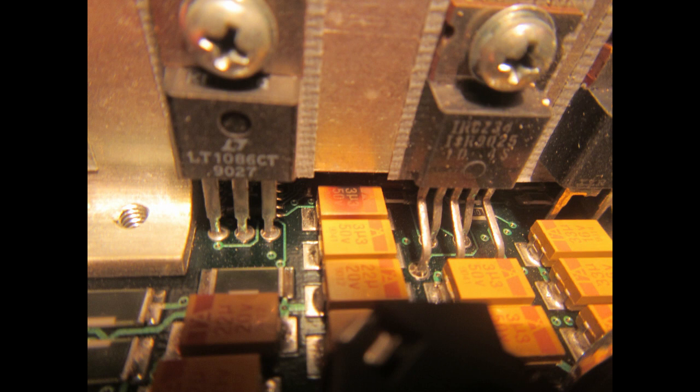A good troubleshooting should always begin with a careful visual inspection of all the boards. And sure enough, that dark spot on the yellow SMD tantalum capacitor is suggesting that it may be part of our problem. Unfortunately, that capacitor is right under the big heatsink.